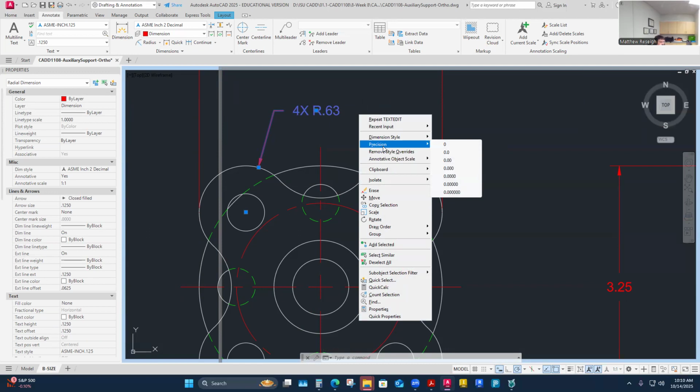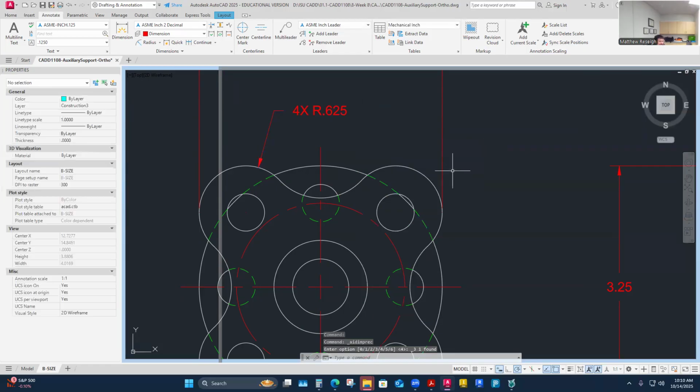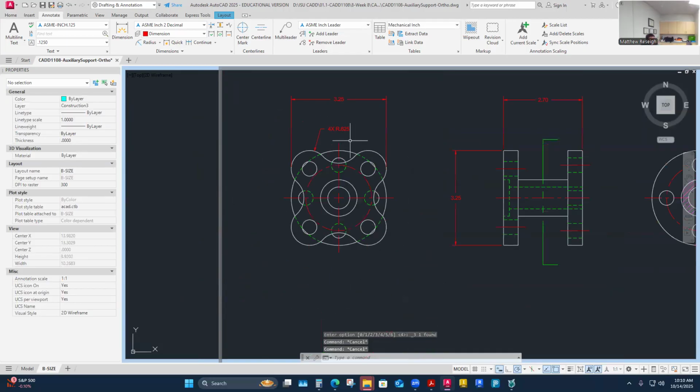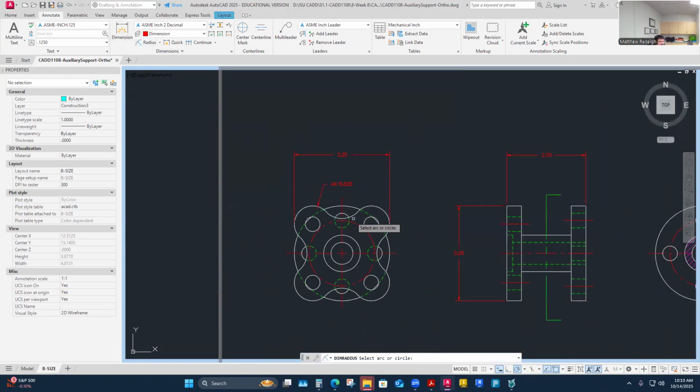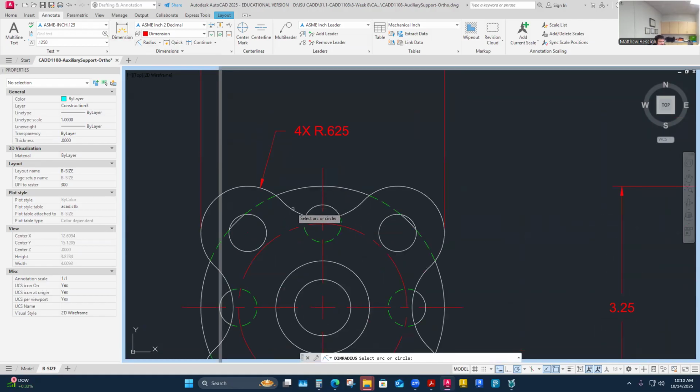I just tend to use it from this little quick access menu here, and I'm going to push that to three decimal places. Now I'm not decreasing the accuracy of this part unknowingly, right? I'm paying attention to what dimensions I was supplied with and maintaining that same accuracy. So that's four times of those. Then I have the inner one as well, and maybe I'll just try to bundle and save here, kind of close. Whether or not this becomes overdone or not.